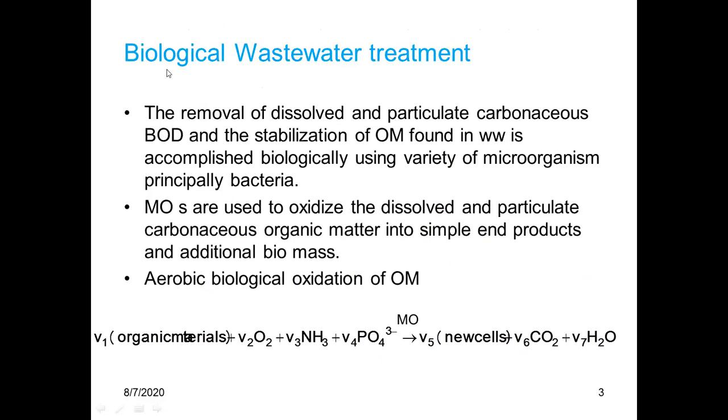So now we know that from biological wastewater treatment, we can remove dissolved and particulate carbonaceous BOD. All of you know BOD is the amount of oxygen required to degrade the organic matter biologically. So this represents the removal of dissolved and particulate carbonaceous organic matter.